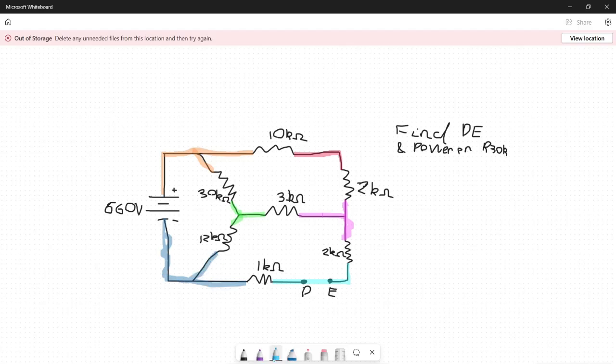So now we can understand what the circuit potential looks like, where the potential keeps changing. The issue is now we need to see where the current is flowing, because as you notice, DE is an open circuit. So the branch that contains DE will actually have no current flowing in it. And where does this branch start?